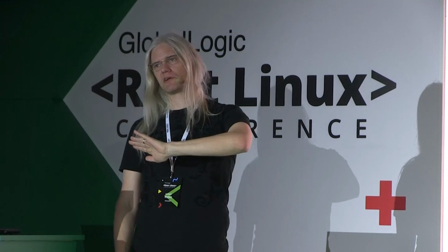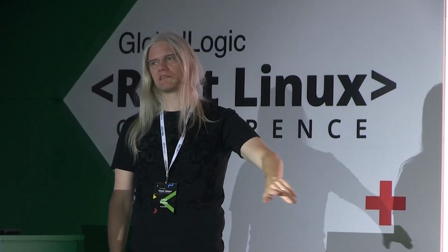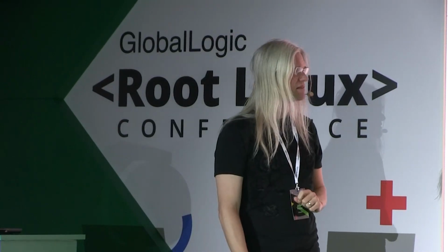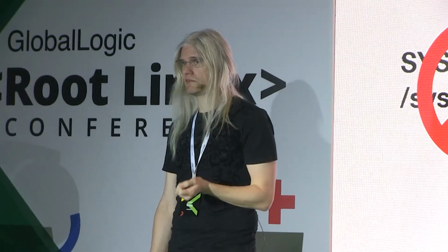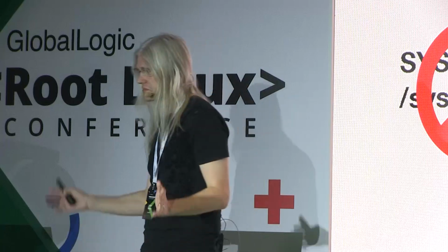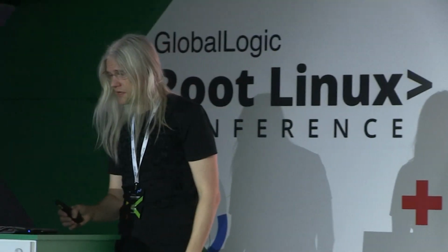The second thing I'm going to talk about today is pin control, and we don't have a user space interface for that. And I'm not really sure that we should have. We should maybe have some of the pin configuration things for electrical properties, which I'm getting to, in user space. Maybe, maybe not. Depends on the use cases. Multiplexing, pin multiplexing, which is the other big thing that pin control is doing. As far as I can tell, it has no place in user space at all. No value to user space. But I have been wrong in the past.